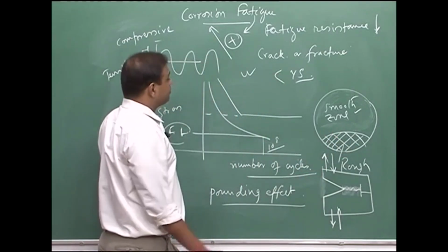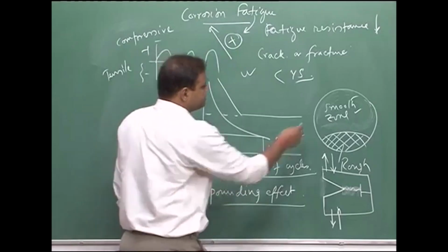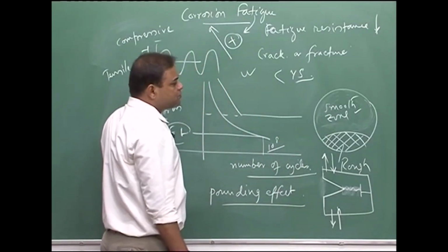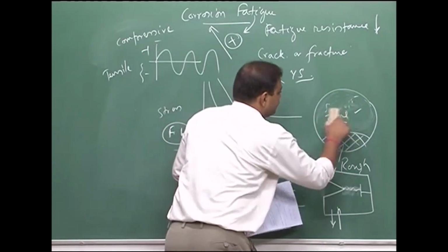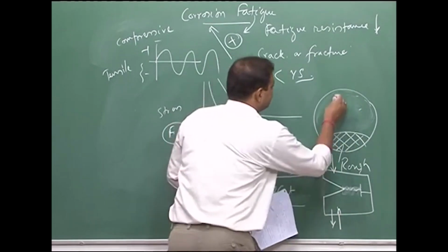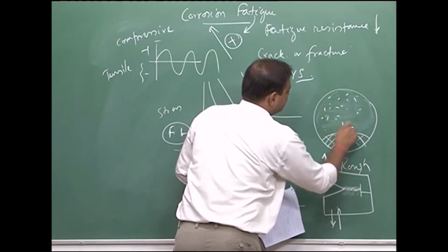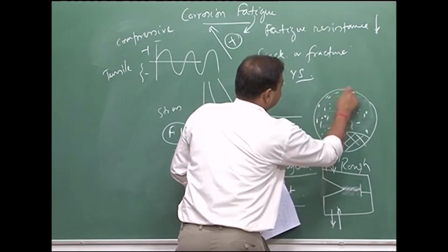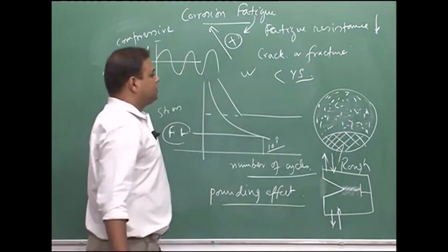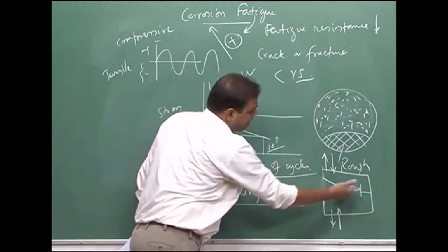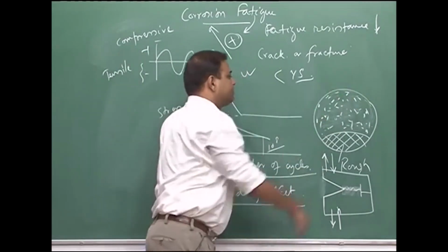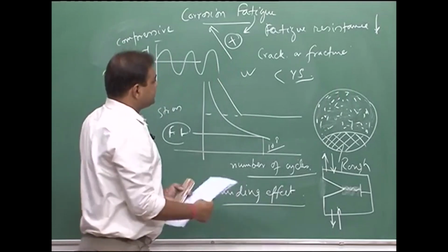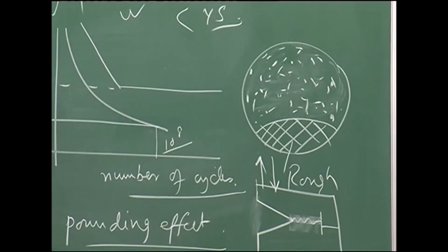At the same time, if you have corrosion together with the fatigue phenomenon, this smooth zone would not look like a smooth surface, rather you will have corrosion debris or corrosion product on this material. For example, those are corrosion products. These corrosion products would form on this zone where you have the crack propagation via fatigue action, as well as the corrosion happening. So, you have the corrosion deposit. This is the fracture surface appearance if we have corrosion fatigue.